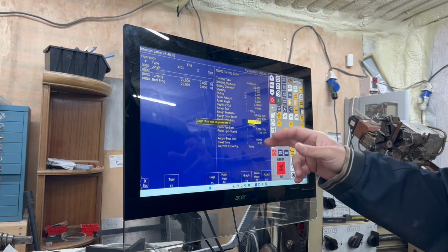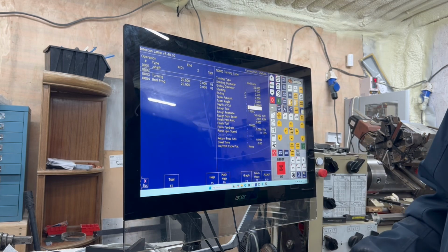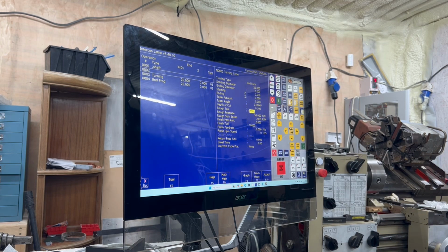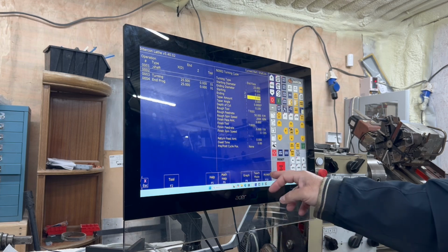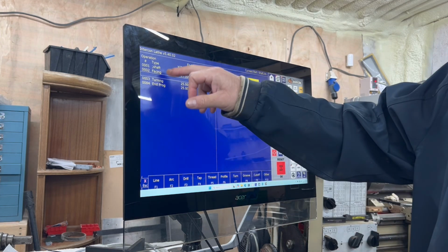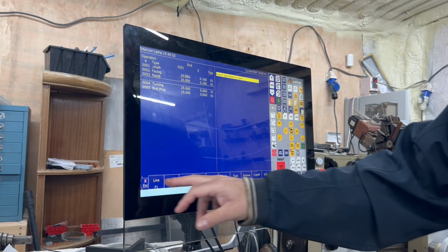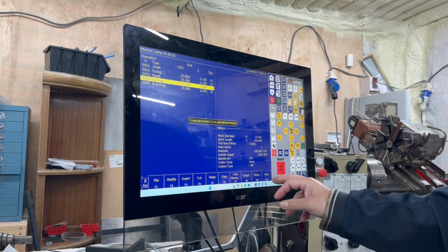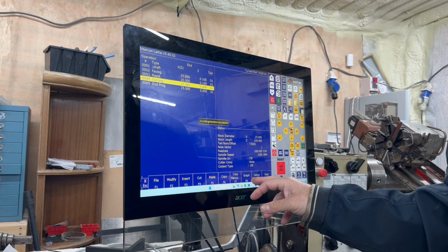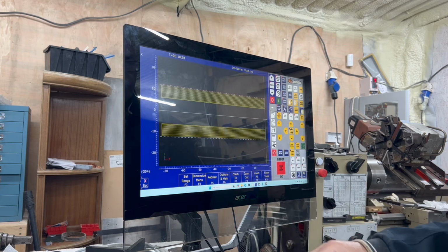Depth of cut, okay. So let's do a 0.1 there. Now, let me do 0.1 there, because I think the Conversational will dislike that if I don't. So now we've got facing, then turning. So what we can do is go back, accept that, post that, and let's just see if that is the same as the graph job.